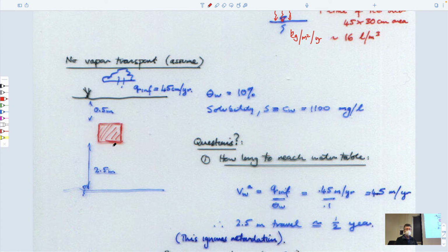So what we could do is we have this. We could calculate how long it would take for the water to get from infiltrating here to going through this region, 2.5 meters, at half a meter depth. And so once it arrives here, then the rain, if you think about it, in this material here, we'd have a profile. If you think about the saturation versus elevation distribution, it would look something like this, right? This is saturation of water, 0, 1. This would be the amount of water that is present there. In the tension saturated zone, this is the amount of water that is there.